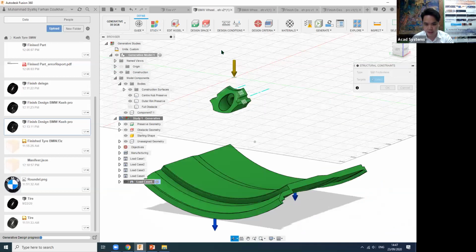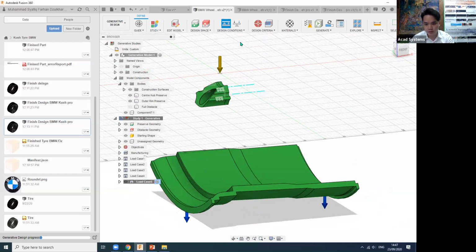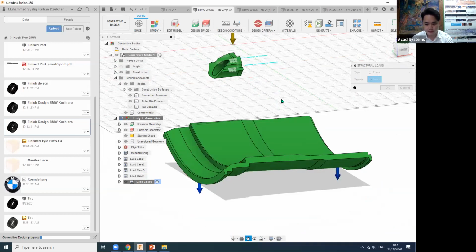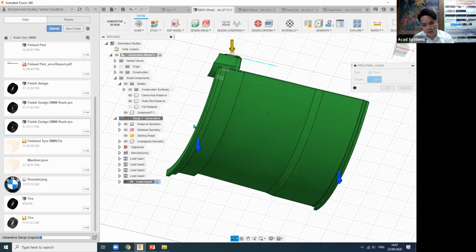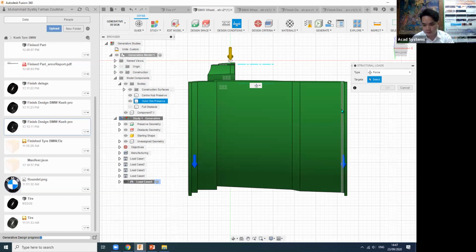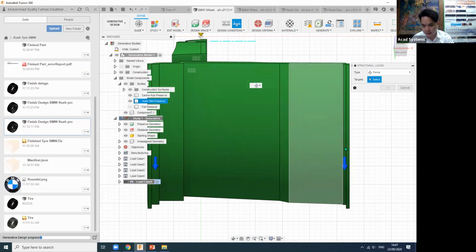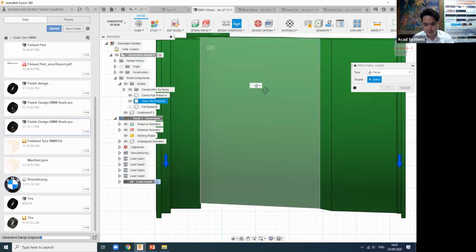To where there will be the second one, which will be the structural load. For the structural load, I will choose here. Some people will ask why I don't choose the middle one. Because when the tire is put inside and I'm rotating, normally the force only applies on the two outer spaces. This is why we are choosing here, this area and this area.